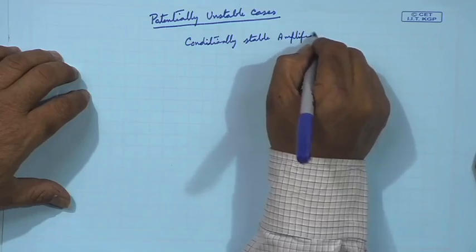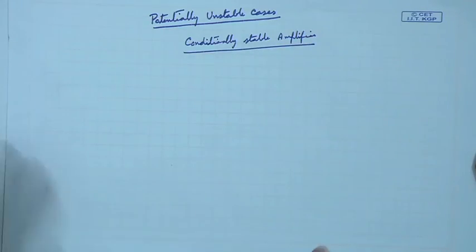We need to demarcate some zone of ZL, ZS, etc., that we won't touch, and we will also demarcate the zone from which we can choose ZL, ZS. Those are called stability circles: drawing them and determining the region where it can be conditionally stable.